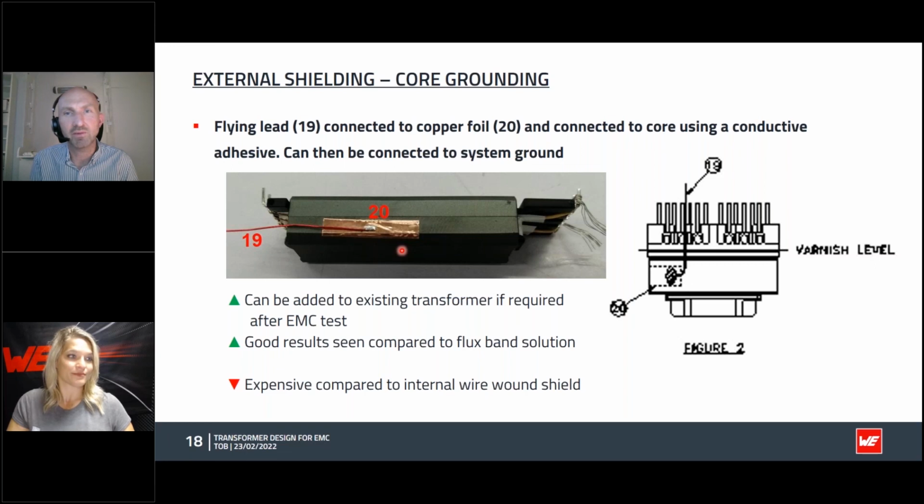Yeah, I would definitely say yes. As regards EMC emissions, with leakage inductance we have one spike and a little bit of ringing afterwards, and then usually you have to dampen that spike anyway with a snubber, and you try to reduce the ringing, but it's usually just at a certain frequency or maybe a couple of frequencies where you have a problem, and that can be often easily filtered.